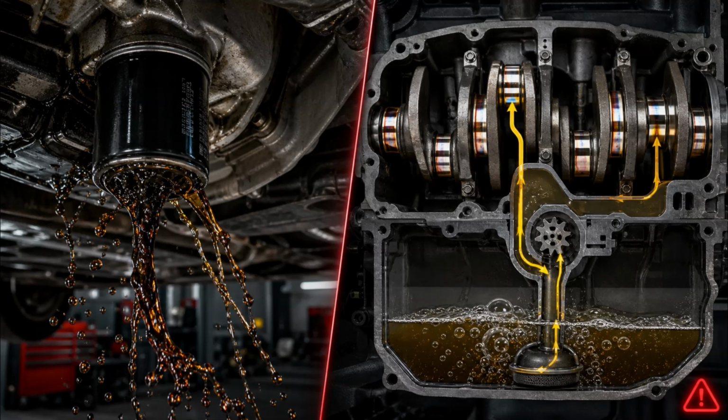If you install the wrong oil filter, the best case scenario is simple: it does not fit, leaks immediately, and you catch the mistake before driving. The worst scenarios are the ones that look fine at first. A wrong thread or gasket can create an oil leak. Engine oil is under pressure while the engine is running, so a bad seal can dump oil fast. If the oil level drops too low, the oil pump may start pulling air instead of oil. That is oil starvation, which means engine parts are not getting the oil film they need to stay separated.